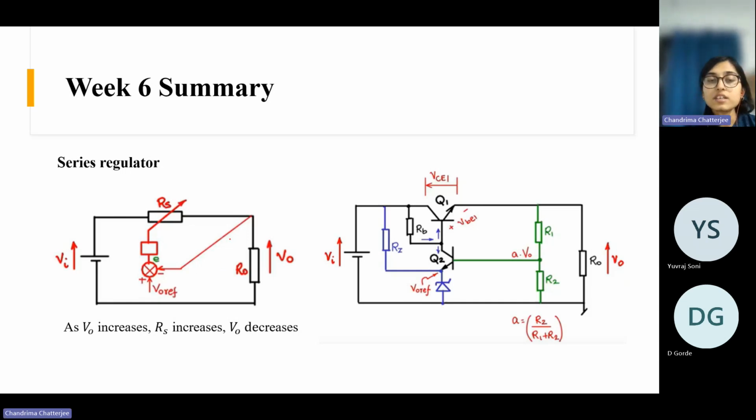And the working principle is, suppose you want to maintain a constant voltage here, irrespective of the fluctuation in the input side. So what you will do is there will be one controller. So here you will tap the output voltage and you will give a feedback. This is a feedback, okay. So this is minus and there will be one reference voltage, that is plus. And the difference of this reference and output, that is called the error. So this is the error.